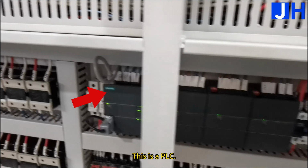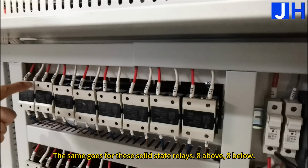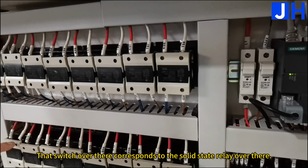This is a PLC. This is a solid-state relay. These switches correspond to the heat switches in the temperature zone above. The switch below corresponds to the switch in the temperature zone under Reflow soldering. This has 8 switches above and 8 switches below. The same goes for these solid-state relays: 8 above, 8 below. That switch over there corresponds to the solid-state relay over there.